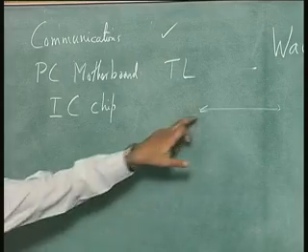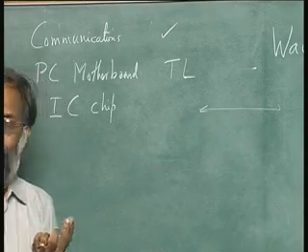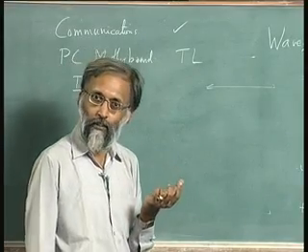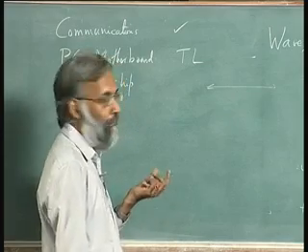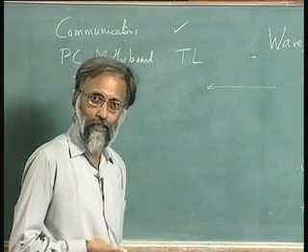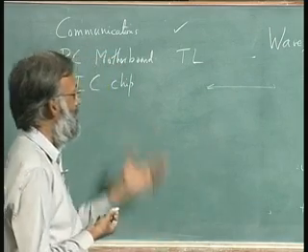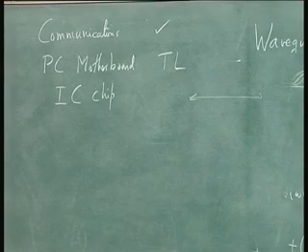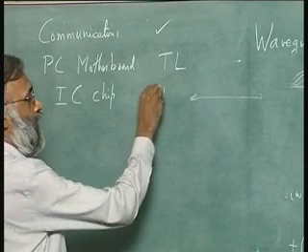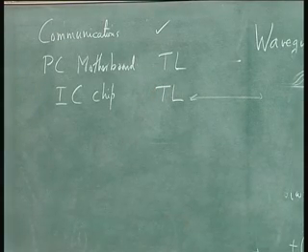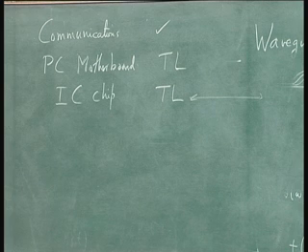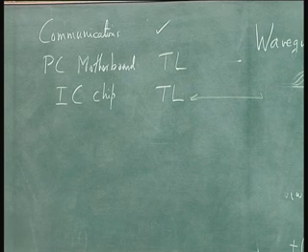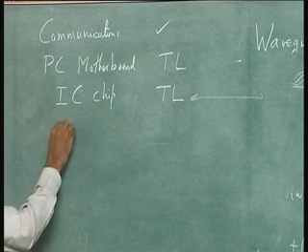What about an IC chip? Well, these distances of lines are now in tens of microns to hundreds of microns, but the speeds are much higher. Because the speeds are much higher, once again signal propagation delays are important, and you have transmission lines once again. So you come lower in frequency, and you come to power lines.